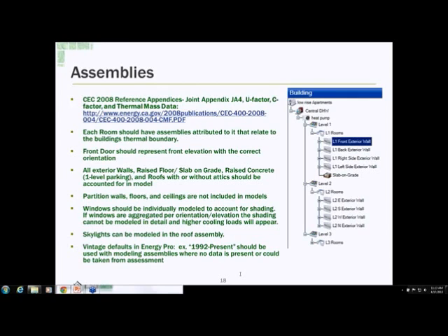But it'll still run the calculations. It's just a warning. But there are calculations that'll stop you, like if you set the occupancy type to multifamily and you're actually doing a high-rise calculation, it will stop you and say, no, I can't do this calculation because you have the occupancy set to multifamily, not high-rise. And you have to go in and change that in order to run the calculations.